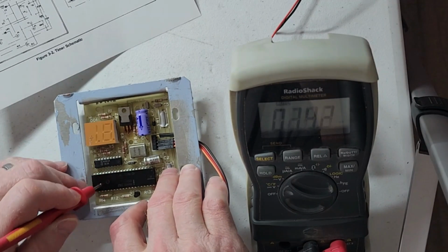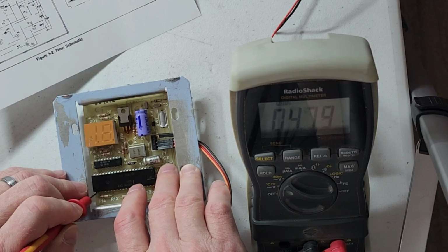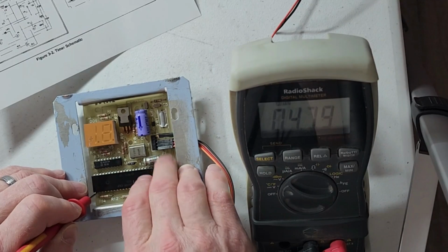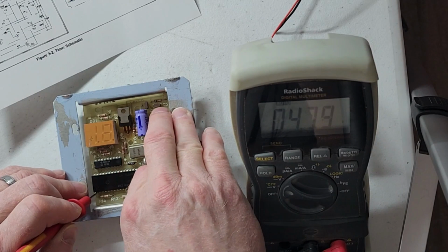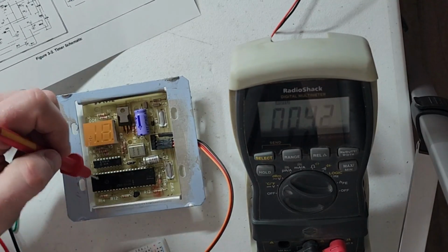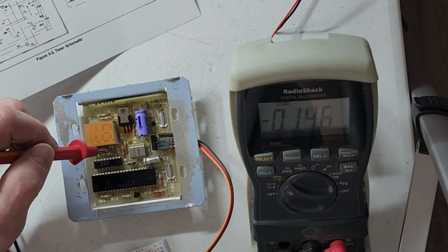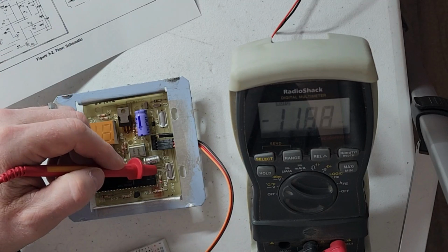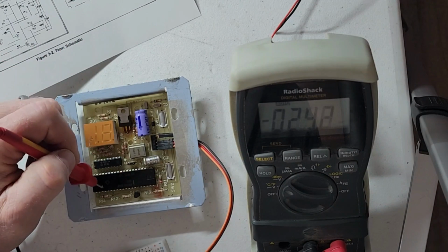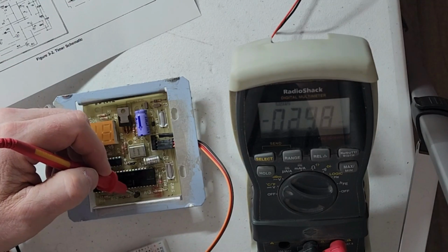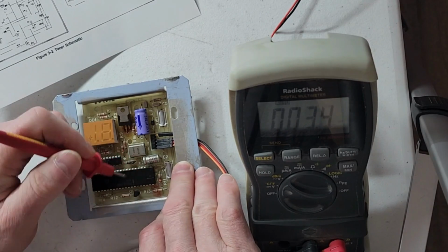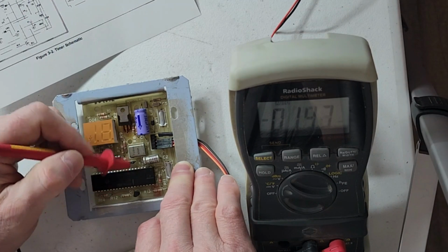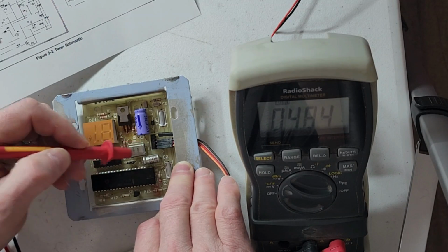Let me see. This is the off-on switch right here. So if I put this on here, we got our 4.8. It does nothing. And we know the switch is working. I really feel like the program's corrupt in this thing. It does display an L at some point. Looks like there's something in here working, because it does detect these switch closures, but it doesn't do what it's supposed to do. Yeah, so this transistor, I'm assuming it's working, because I don't think we need to take that any farther at this point, because the base is on, the power is going through to this lead. So I think that's good.